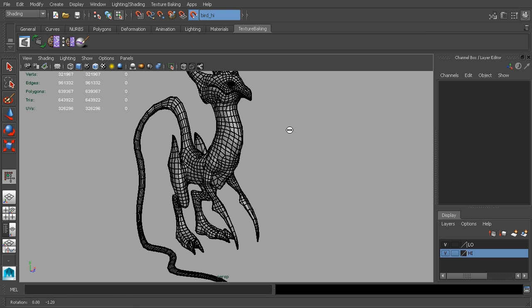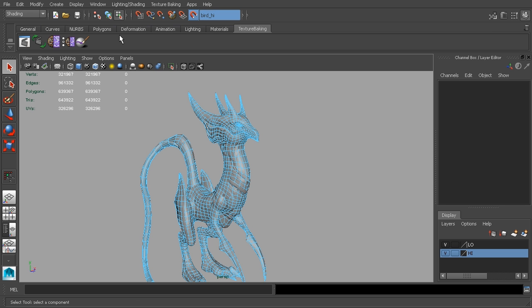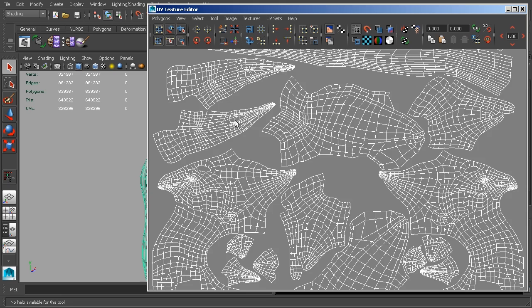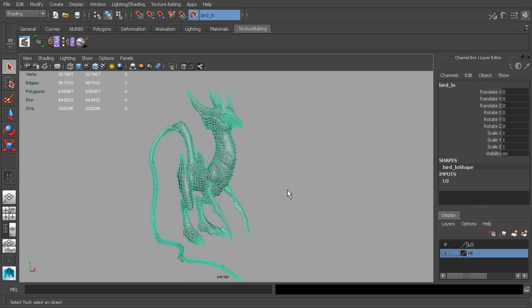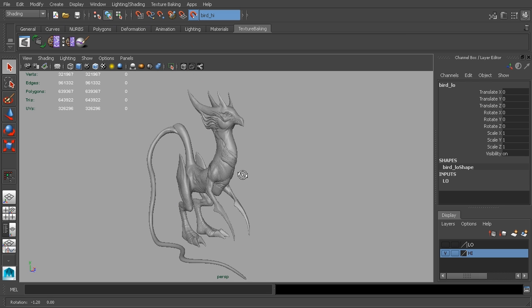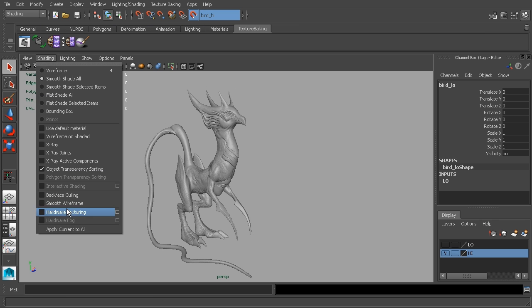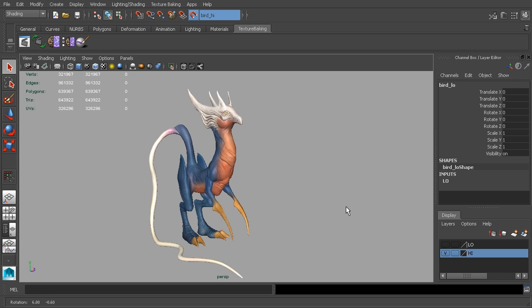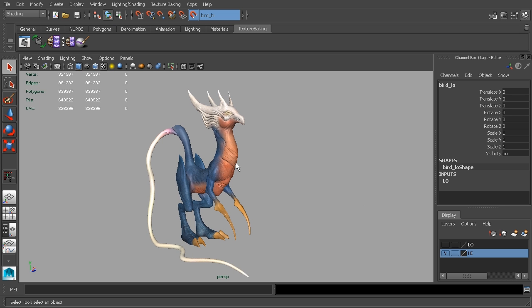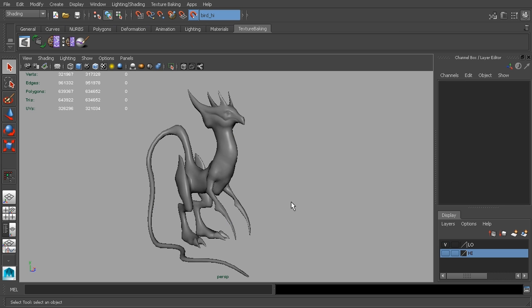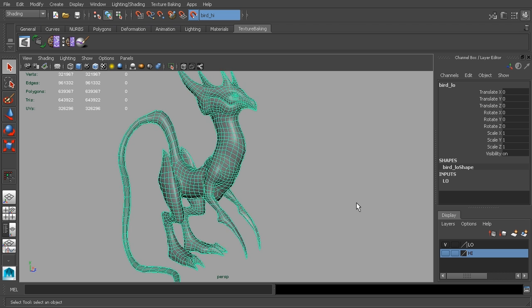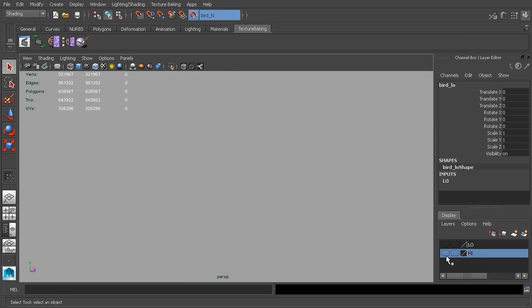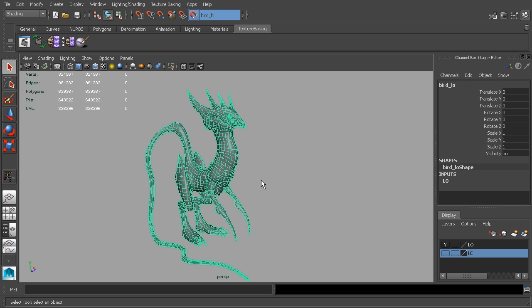And before we do that, we would want to set up a UV layout for our geometry. So in this case, if we take a look at this, you can see that it does have a UV layout over one tile. So the idea here is that we take the detail from this high resolution model, and you can see it does also have a color texture associated with it. We take that detail and we transfer the sculpted detail and the painted detail onto the low res. Now, the low res has the right shape, and it's good for what we want to do as far as the rigging and animation and moving through the pipeline. We just need it to look more like this one, which means we'll have to bake out maps.